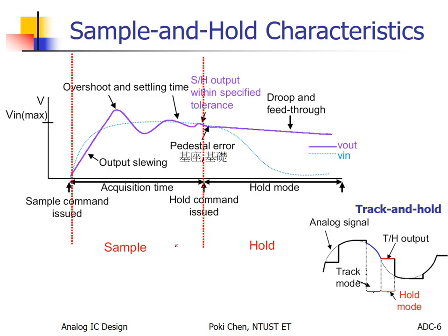And then we can go for this. Before quantization, I told you already, we need to do such kind of sample and hold. Because during quantization, if your input is still changing, sometimes that is harmful for your result. We can prove that during quantization, if the input is fixed, usually you can get better accuracy. And this is the reason why we need sample and hold.